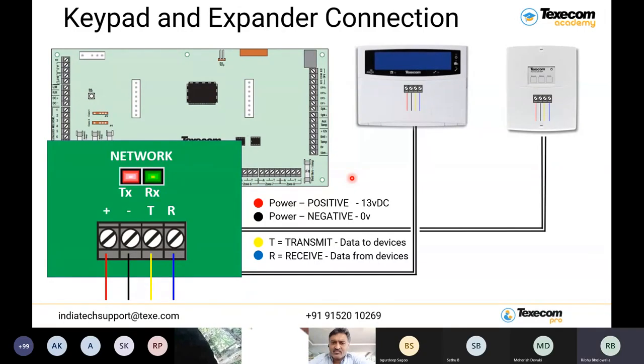Along with that, I just want to add that you can do the wiring in star connections or in a daisy chain wiring. Both connections are possible. Star means all the devices are connected individually. The keypad wire is coming individually, the expander wire is coming individually to the control panel. This is called star.